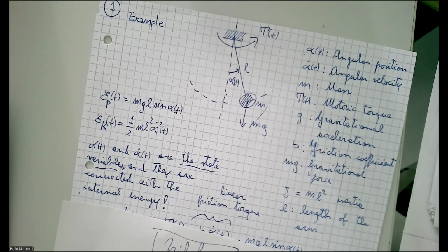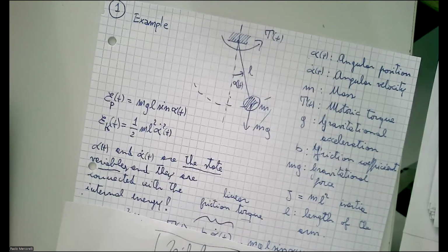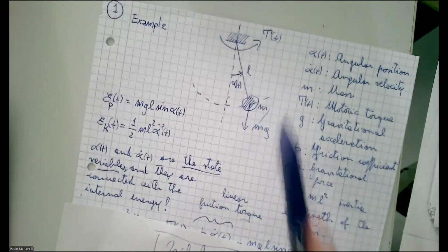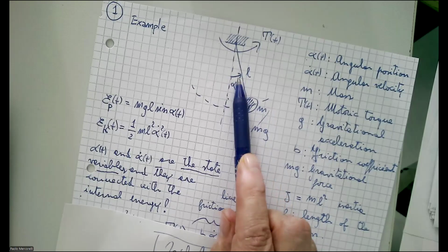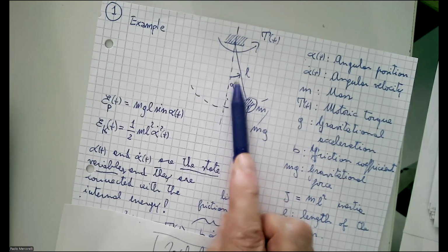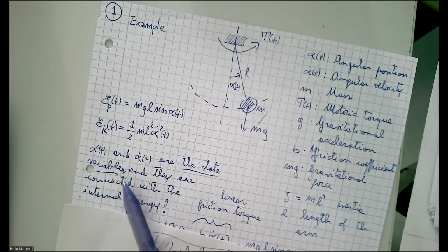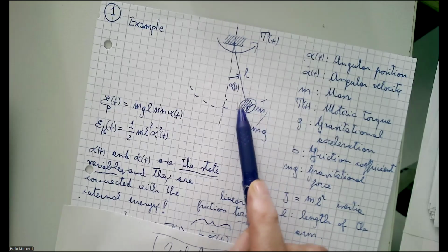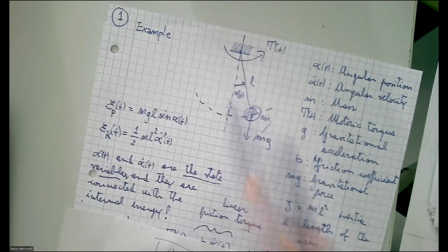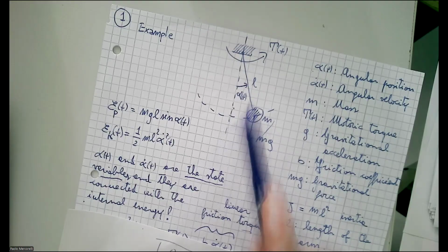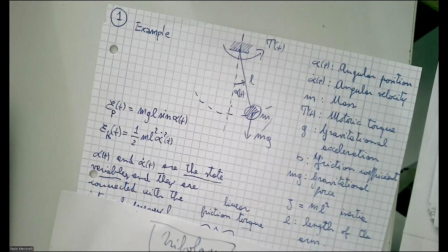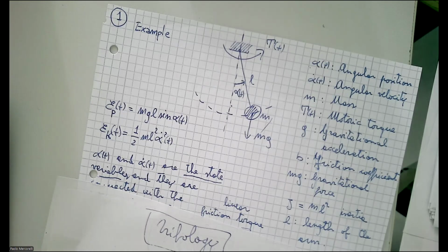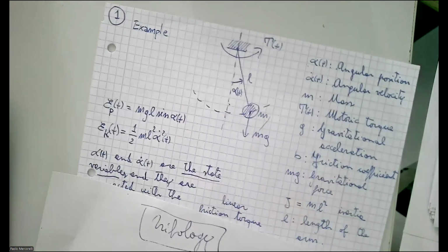Let me see. I forgot to say something. Yeah, the orientation. But this is already known from physics, from technical mechanics. I have to consider a positive direction of the position, which is also the positive direction of the velocity, angular velocity and angular position. And in this sense, typically, but not necessarily, but easy for the representation, we consider also in the same direction the inputs, in this case, the torque, positive, let me say, anti-clockwise.